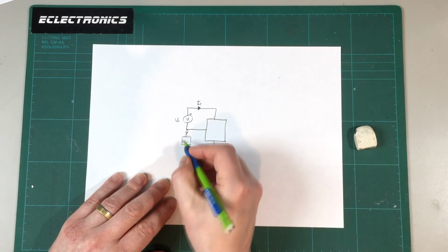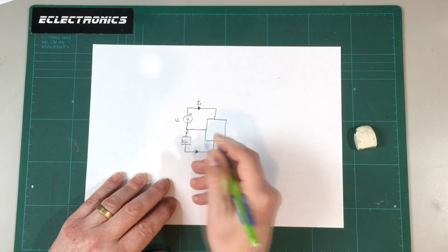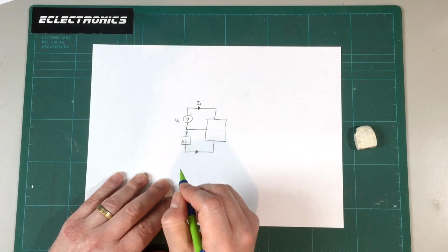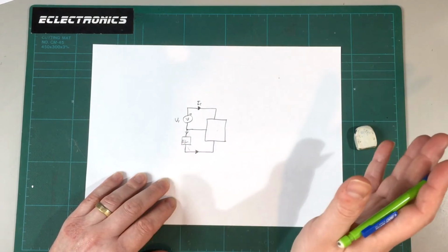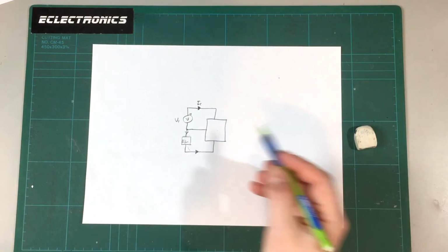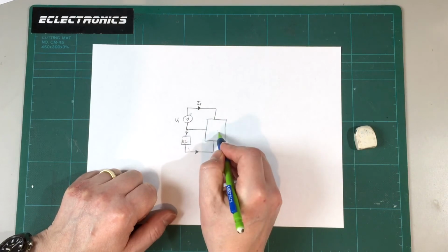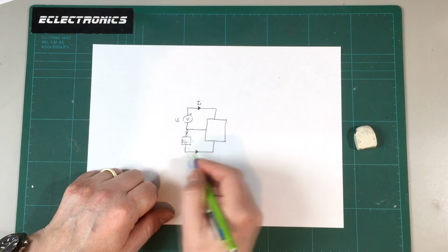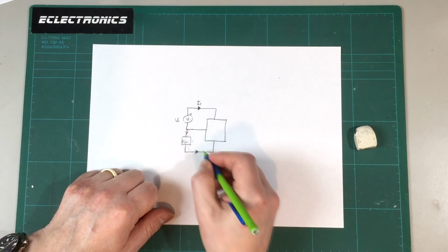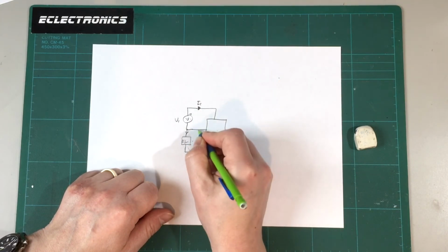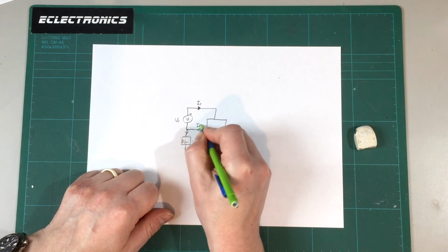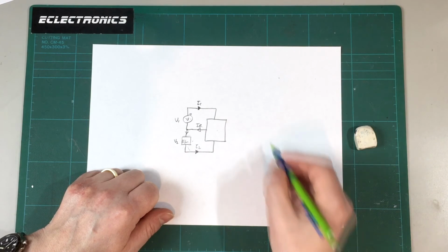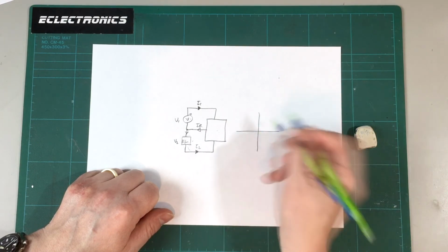So here, if we've got an electronic device which is keeping the potential fixed, this circuit should be a lot happier, I think, doing that. So my plan, in the next part of this series of videos, is to try connecting up the charge balancing circuits with a power supply and electronic load in this configuration, and then measuring I1, I2 and IB, obviously V1 and V2 as well, and plotting those characteristic curves and see what we get.